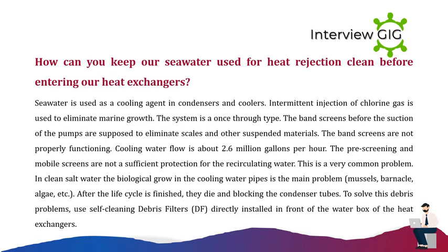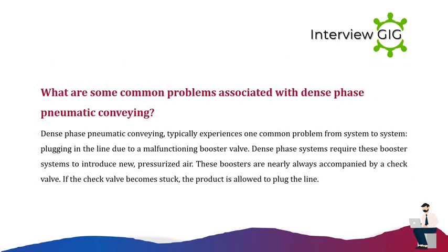To solve this debris problem, use self-cleaning debris filters, DF, directly installed in front of the water box of the heat exchangers.